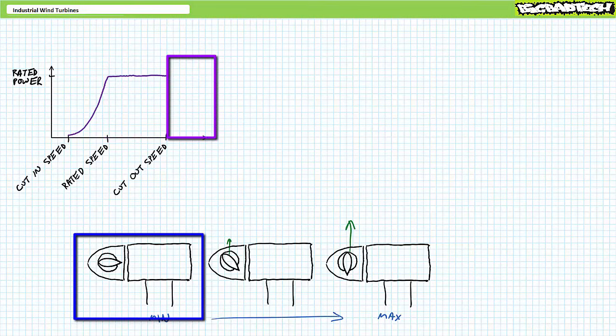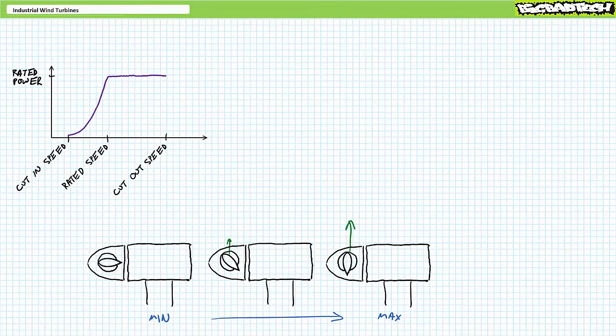At speeds above the cutout speed, the turbine effectively ceases production by aerodynamically braking the rotor with an extreme blade pitch angle, and if this isn't enough, it can take additional steps to protect itself, such as yawing, or turning out of the wind. Yawing out of the wind is sometimes known as furling. Additional mechanical and electrical means, which we'll examine in a moment, can also decelerate a moving rotor and, if necessary, hold it in place.